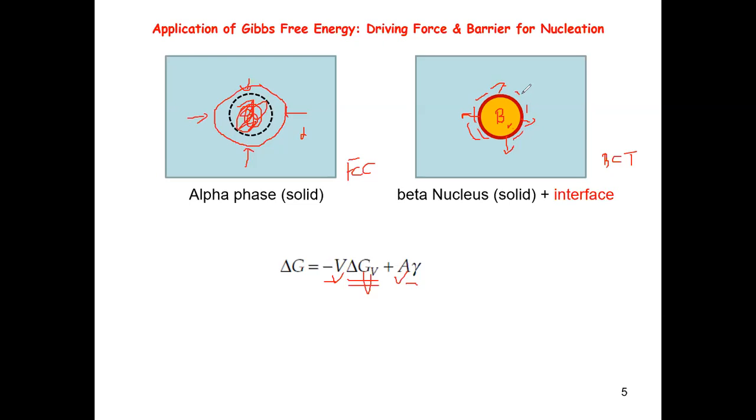Professor, I have a question. Sure. This is assuming that the beta phase requires a higher volume, right? What if it's the other way around? What if the beta phase requires less volume than the hole that we've created? When the beta phase has less volume, the beta phase is going to pull everything in.